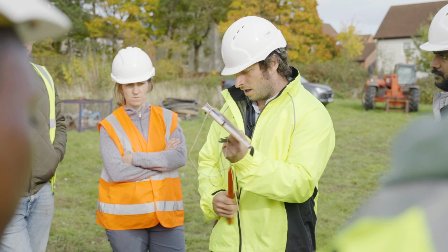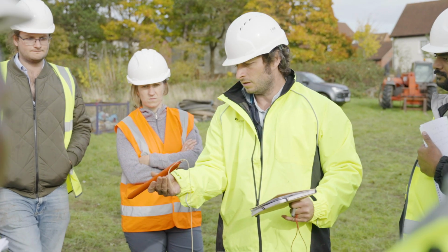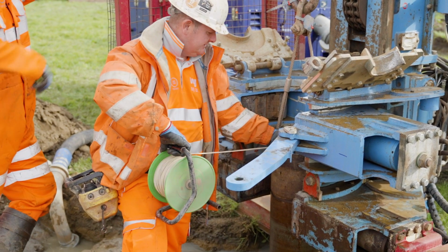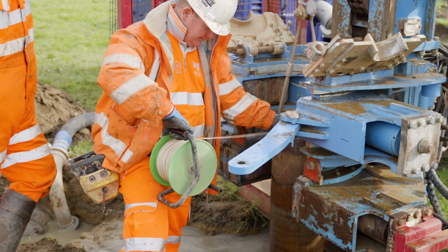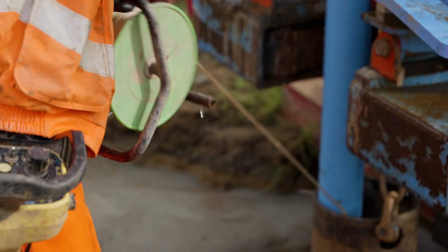The tagline, or the plumb line, is your eyes down the hole. It's a highly valuable tool for the drilling supervisor. Groundwater Relief designs their own plumb lines based on weights of 700 to 1,000 grams using Kevlar rope and reels. Before installation of the casing, the borehole depth should be measured.